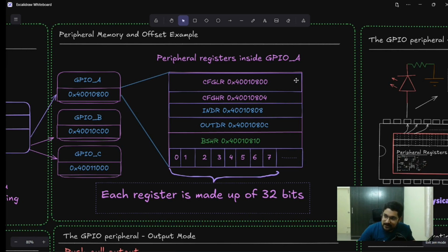Now, if you see, each of these registers differs by exactly 32 bits. So the last address is 0, the next is 4, which means there is a 4-byte gap, and a 4-byte gap again, and again. And I'm showing the least significant bit first. The datasheet might show the reverse. But just understand that these are bit addressable, and each bit, not byte, each bit in a register means something, or it is reserved. All right?